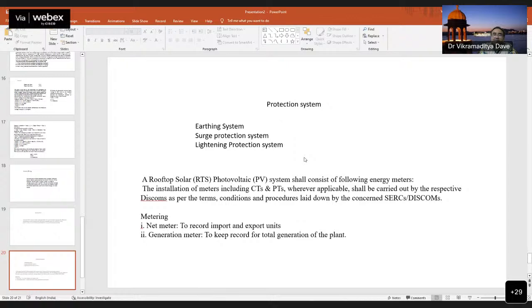we can say a good thing. And if it is greater than 5 to 10, then maintenance is required for your earthing system. And if it is greater than 10 ohm, then it is better not to create any earthing system in that area. So it should be less than 1 ohm in the ideal case, 1 to 5 ohm in the practical case, and maintenance is desired where it is between 5 to 10 ohm.